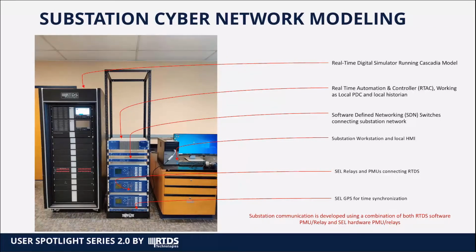We have RTDS, and we have a real-time automation controller working as a local PDC and local historian. We have software-defined networking switches connecting the substation network. We have a substation workstation and local HMI. We have SEL relays and PMUs connecting to the RTDS, and we have an SEL GPS clock for time synchronization, which is taking the time from satellite and synchronizing the RTDS and the devices with a similar protocol.